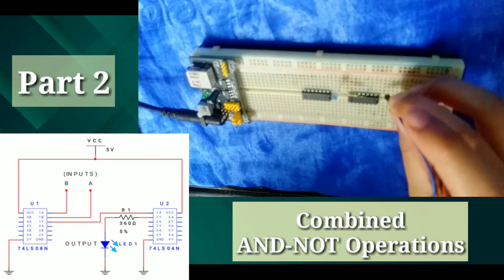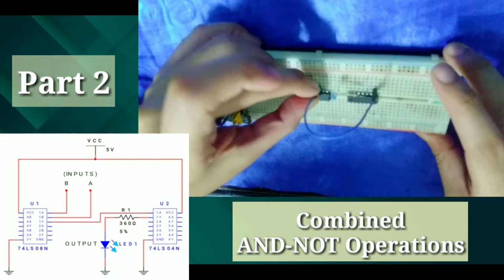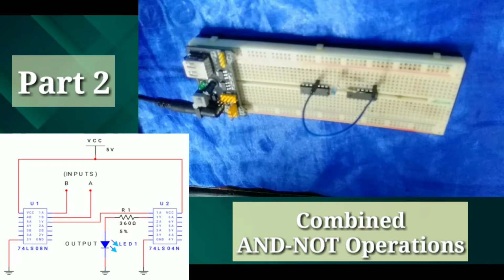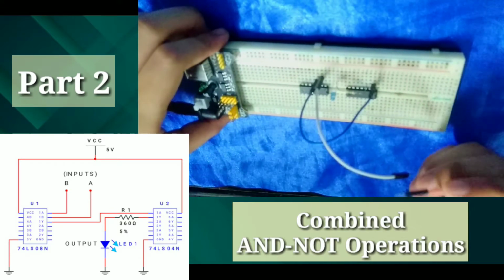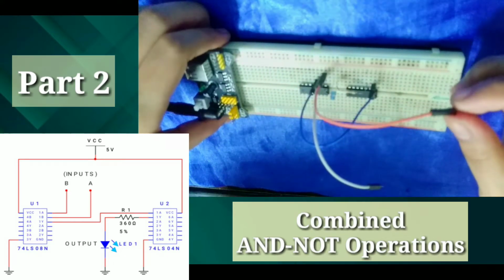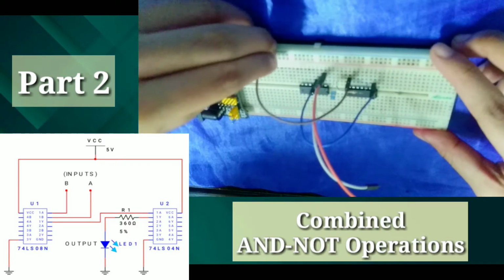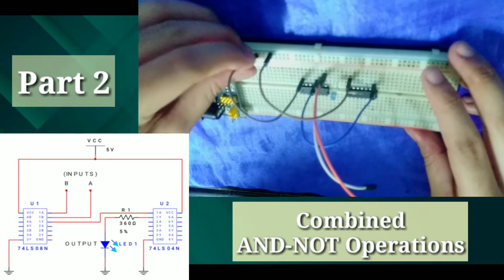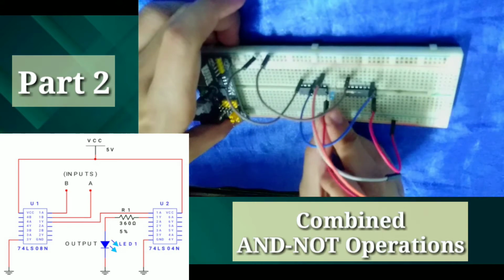Let's connect the 1A pin of 7404 to the 1Y pin of our 7408 IC. Now, input A will be on the 1B pin or the second pin of 7408, and input B will be on the 1A pin of our 7408 IC. Don't forget the proper grounding of our circuit, wherein the ground pin of our ICs will be connected to the ground. And also, don't forget the connection of the VCC of both of our ICs to the voltage supply.